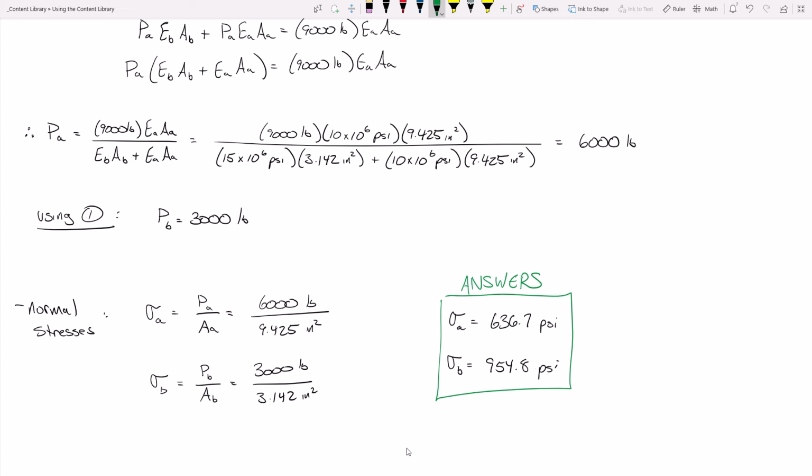There you go, right? So this would be an example of a sound engineering design because the brass is a higher quality material. It can withstand more stress, right? While we are not looking at maximum stresses, a clue into this is to look at the E values. The E value for the brass is larger than the E value for the aluminum, which at a minimum means that brass is stiffer, right?